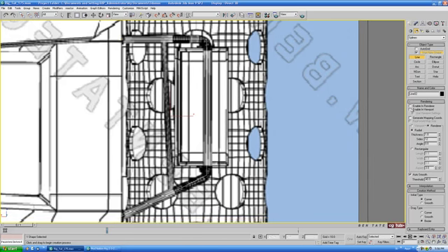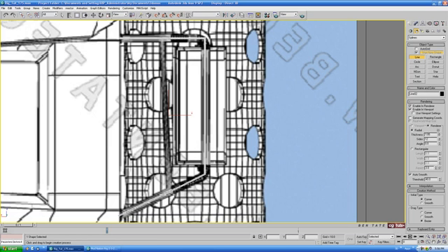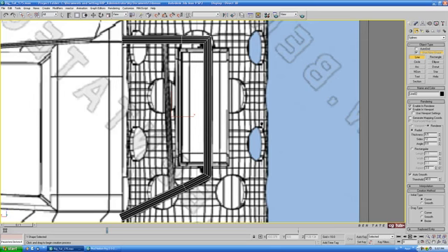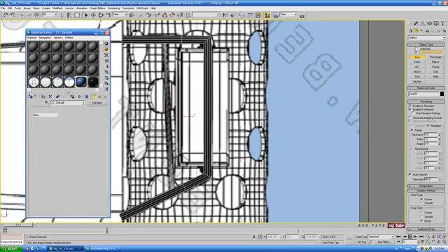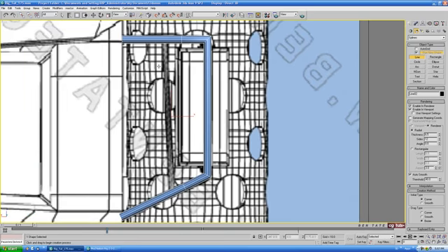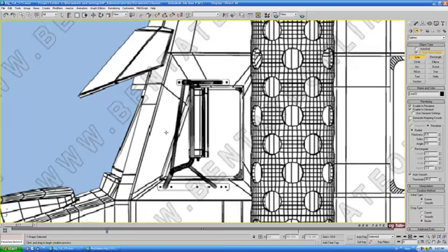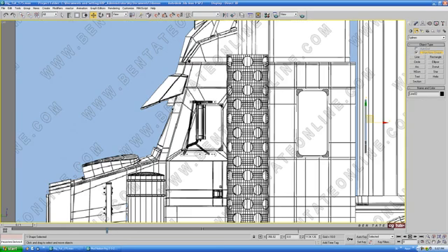Okay, and let's go over into the modify panel here. We'll just enable in render and enable in viewport so we can see the thickness. And we'll take that up a bit. And let's maybe do about 6.5 on this for starters. We'll also put a blue shader on it. And we'll jump into the left view here and just move this to the front.